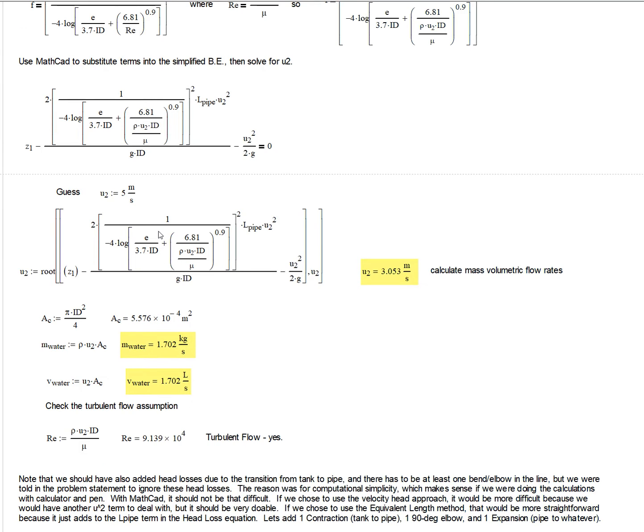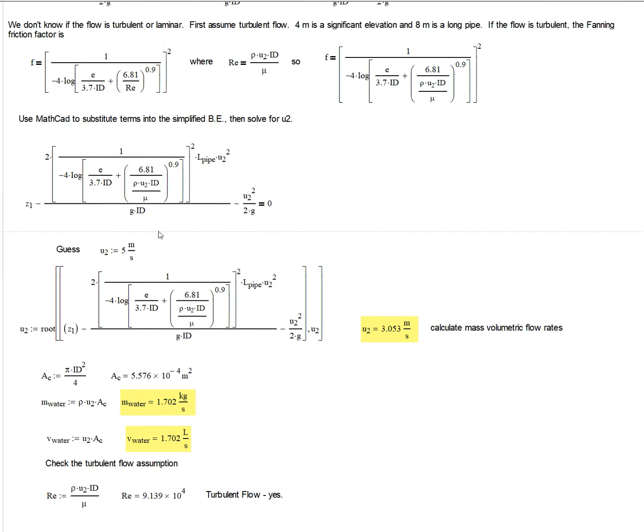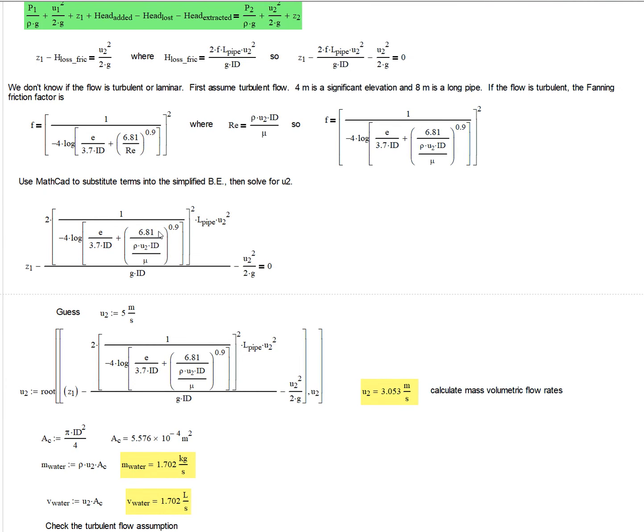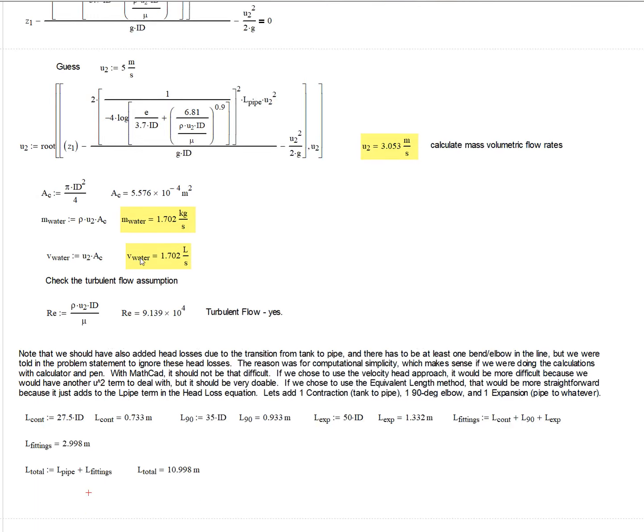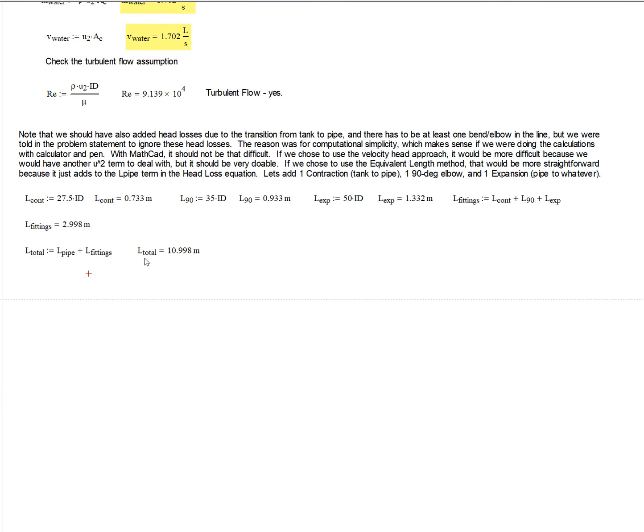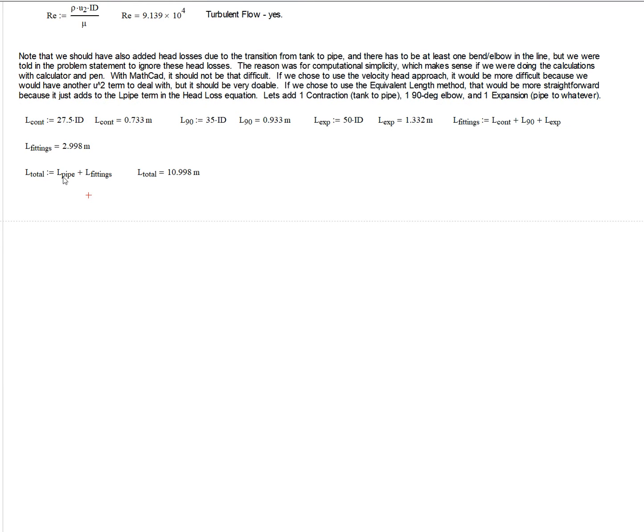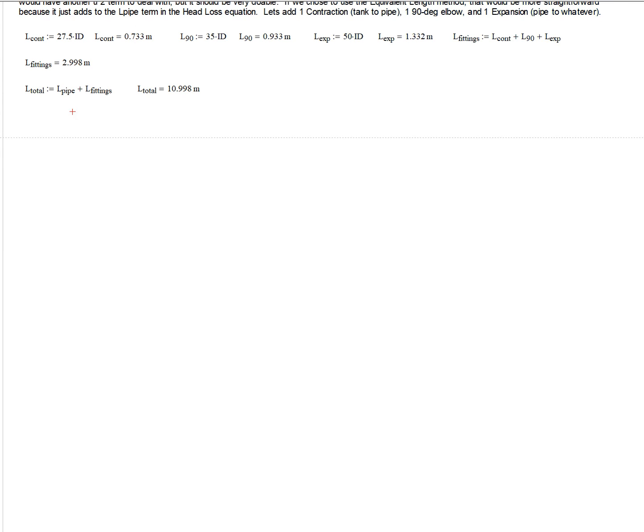If we go up here, we did not explicitly calculate the head loss. So anyway, we can't compare it directly, but this is our head loss due to the pipe plus the fittings. And if we calculate the head loss due to the pipe, that's just going to be 8 meters, right? The equivalent length is going to be 8 meters. And so you can see that it is added about 37.5%. So the fittings would add quite a bit. So anyway, it's not insignificant.